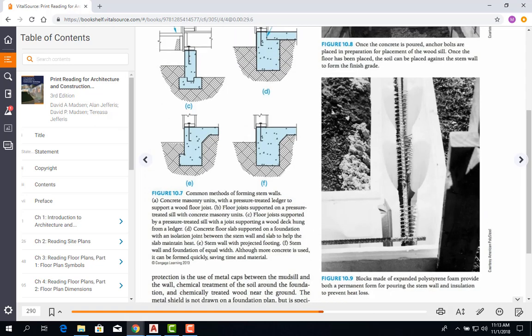The one we do here in the Valley is the on grade. We call it slab foundation. It's more feasible here in the Valley, for the area that we live in. The soil is supportive enough, the water table is not as high, and the soil that we have supports a slab foundation.